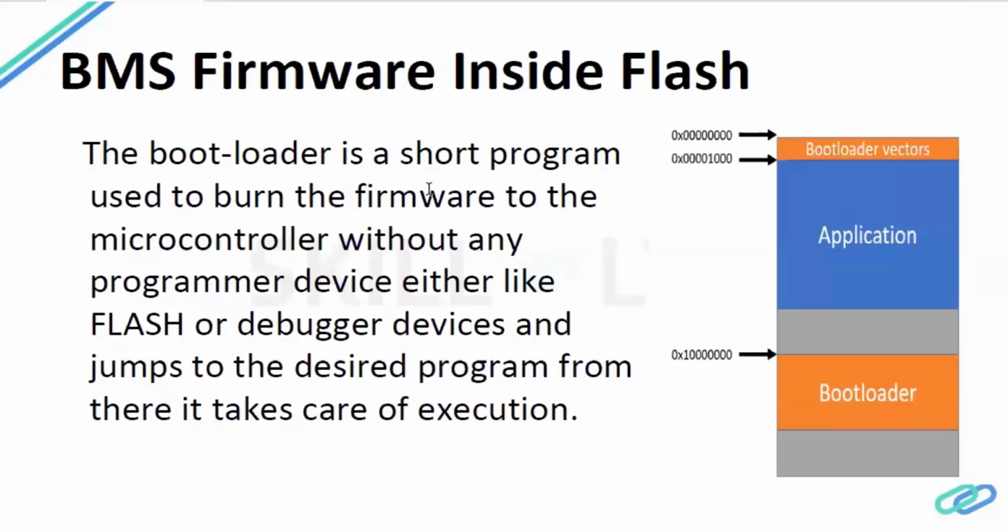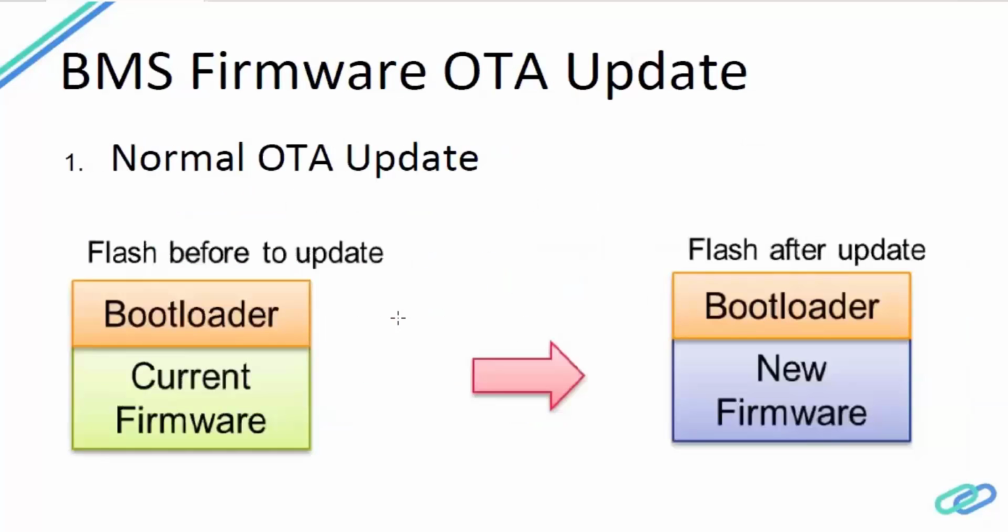So what is the task of the bootloader? A bootloader is a short program used to burn the firmware to the microcontroller without any programmer device, either a flash or debugger device. So you don't need any software or hardware to update the firmware if you have a bootloader inside your microcontroller. We will look at how these things work.